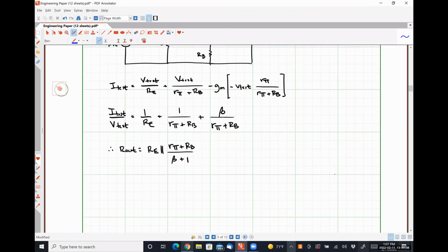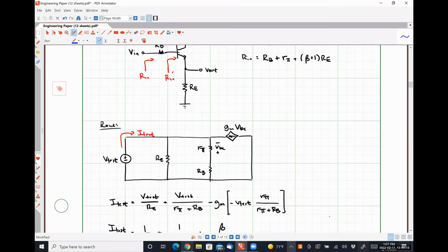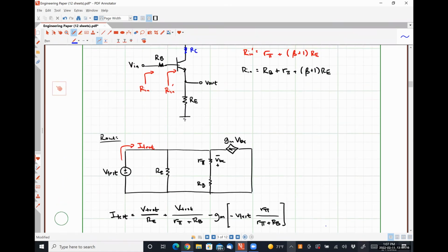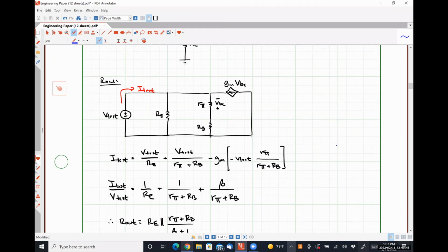All right. So our voltage gain. Okay. So we call this voltage VB. We know the relationship between V out and VB because we just derived it a couple of minutes ago. So what influence is having this resistor RB in place have? Just like all the others, makes a voltage divider at the input.